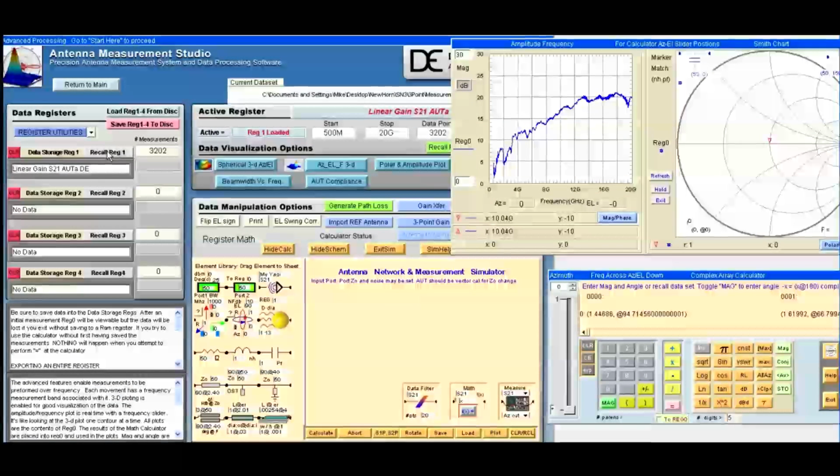Next, we're going to demonstrate generating a lower resolution S1P file on the DAMS DE726 horn. We've loaded measurement data performed in calibration with 3 antennas. The 3 horns are calibrated 3 at a time using the 3-point method. That profile looks fairly typical for the DAMS horn. There are 1600 data points across this profile, and what we're going to demonstrate is how the labels are actually made, which include the lowest frequency of 500 MHz all the way to 20 GHz in 1 GHz steps.